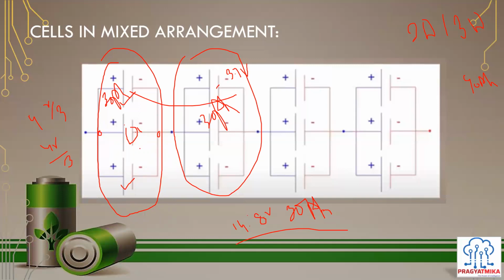Okay. So in this case, if this is the cell whose capacity is fading faster, it is going out of balance. So this would become the weakest cell in this module, right? Yes. So if the discharging or the charging happens, at the time of charging, this cell will get charged maybe up to 90% SOC. This one also got charged up to maybe 92% SOC during the charging, but this one is charged only up to how much? 40%.